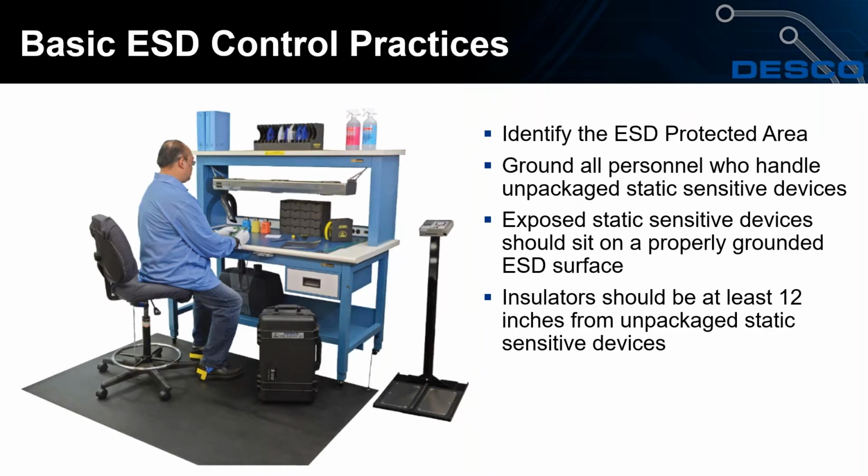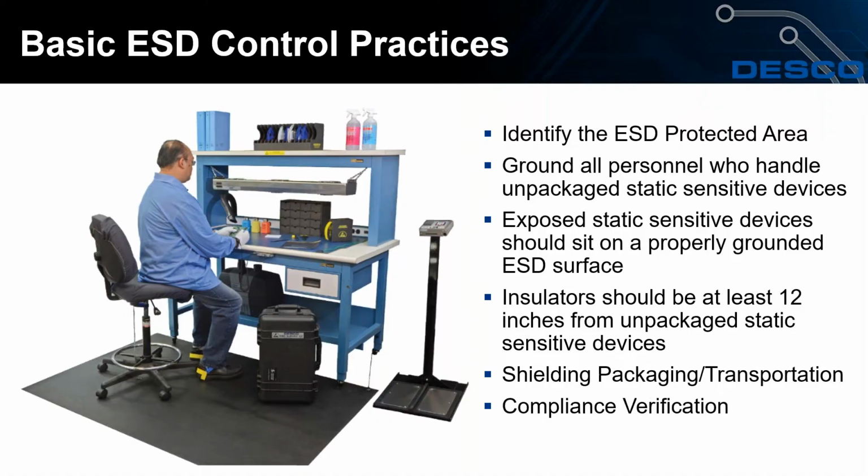We can get rid of them, we can move them far enough away where they're not a threat, or we can use ionizers to neutralize them, which I'll show you. And then packaging plays a big role as far as ESD packaging is concerned in a static control program. If I need to move, ship, or store that ESD sensitive item away from ground, I want to make sure we're putting that in packaging that includes shielding, like those gray metallized static shielding bags or moisture barrier bags, for instance.